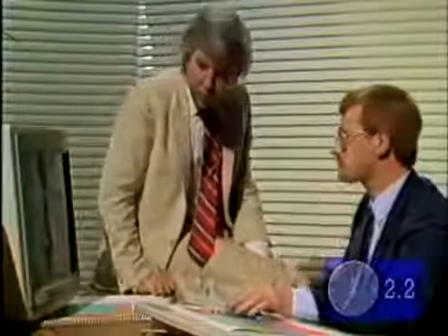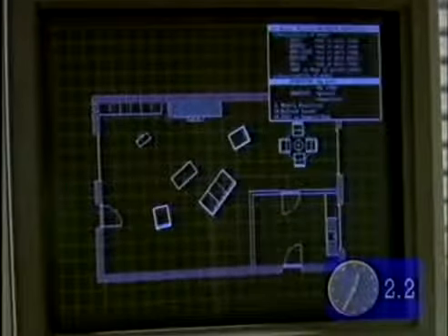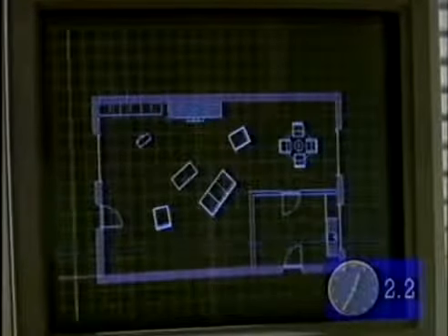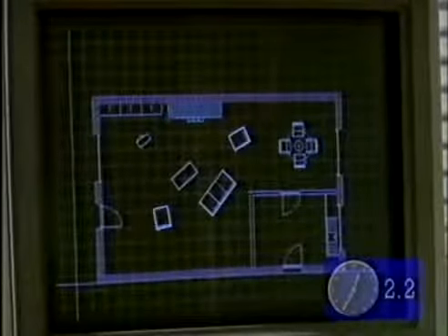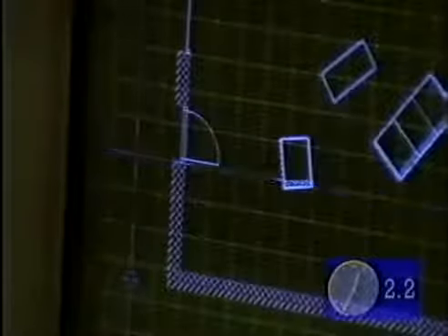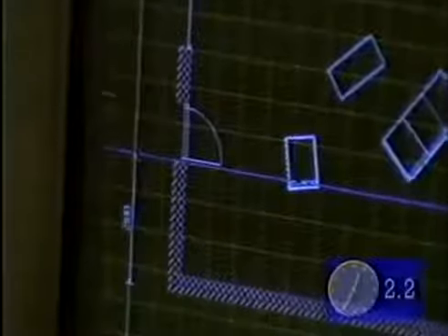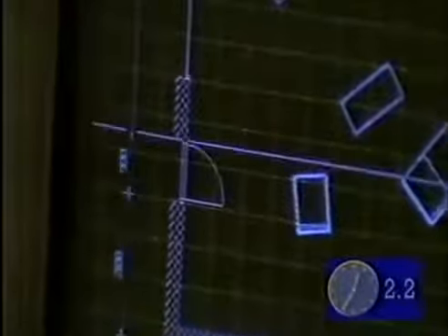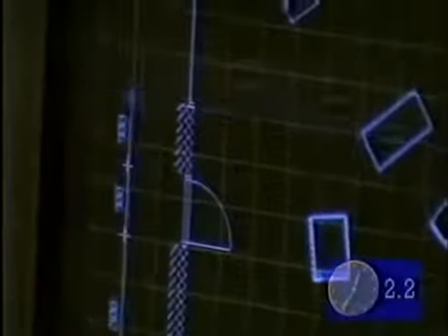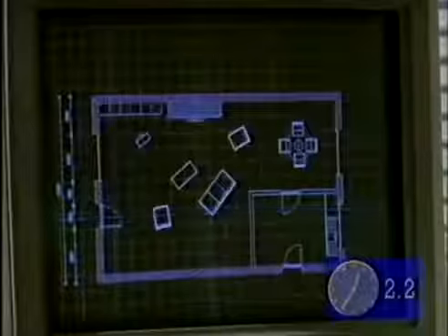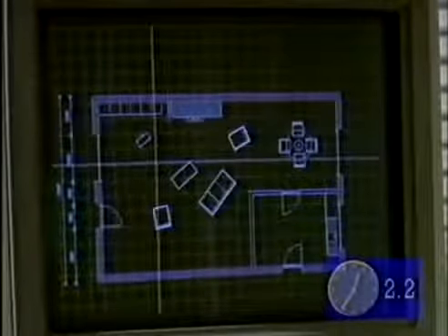That's right. So I'm selecting from the screen menu, dimension by puck, and all I need to do now is simply say start dimension, let's say there, end dimension. Right. And it calculates that distance and puts in the text accordingly. Puts the size on. So it is start, end. Yes. Because the description in the machine is to full size, these calculations can be made directly. That's right. And we can do a total run all the way down the length there. Lovely. And because you know that run equals the total run as well.